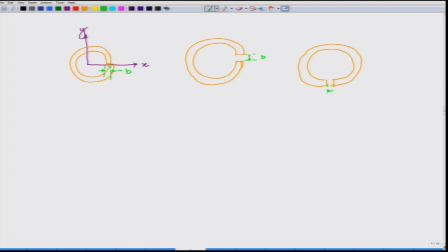So, this is again the two faces, and the translation has taken place along these two faces, which have again been pulled apart. So, this is again the Burgers vector B. These two are equivalent. Now, there can still be a third one which we will show here.